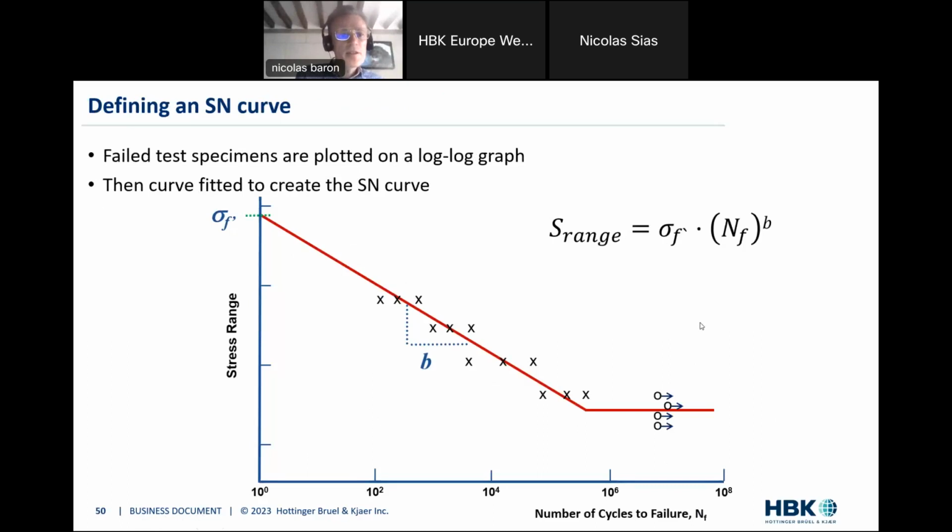So to define the SN curve, sorry, the SN curve, the Wöhler curve, but it should rather be called SN curve. Again, this relates stress values to the number of cycles. We have to make some kind of assumption. This is what we referred to before when we said that fatigue is a statistical phenomenon. And why is it such? Well, you see here that at a given value of stress range, we have three crosses here. And what does this mean?